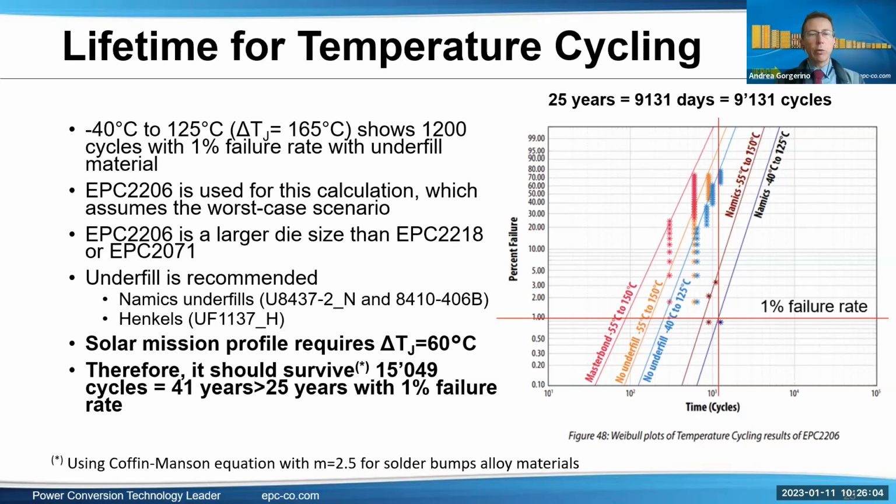So as I mentioned, we do recommend underfill. These are the two that we tested that provide good performance. They're shown in the chart. You have to pay attention to how you pick the underfill. There are quite a few interesting observations and test results in the reliability report. I suggest you take a look at that.